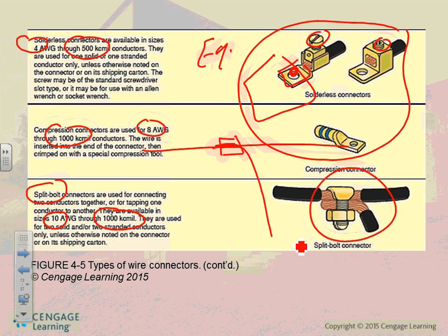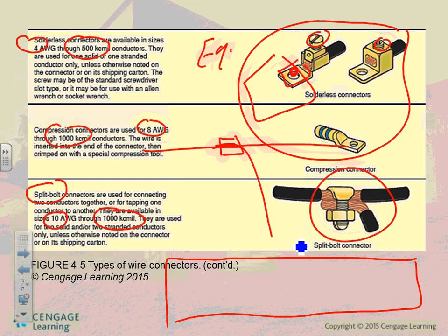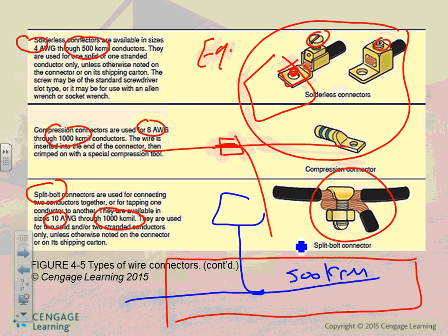So what they do, guys, is they have a gutter like this, and inside it a 500 kcmil, 500 kcmil, right? Now they want to tap this conductor. So what they do, they get rid of the insulation here, they put the cable, and they go to a disconnect, and here's number, let's just say number 6. There's rules for tapping. And the split bolt right here, and when you put a split bolt right here, of course you have to put insulation over it. So you tape it. All these need insulation, especially if they're, depending where they are, especially this one needs insulation.